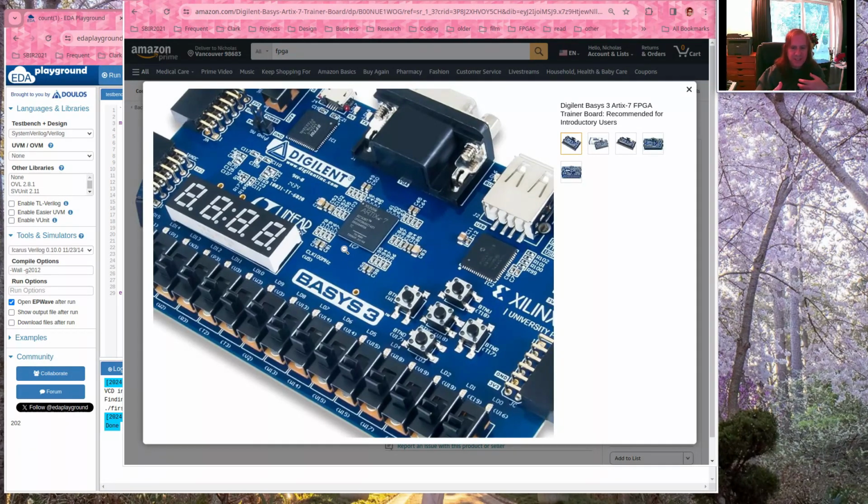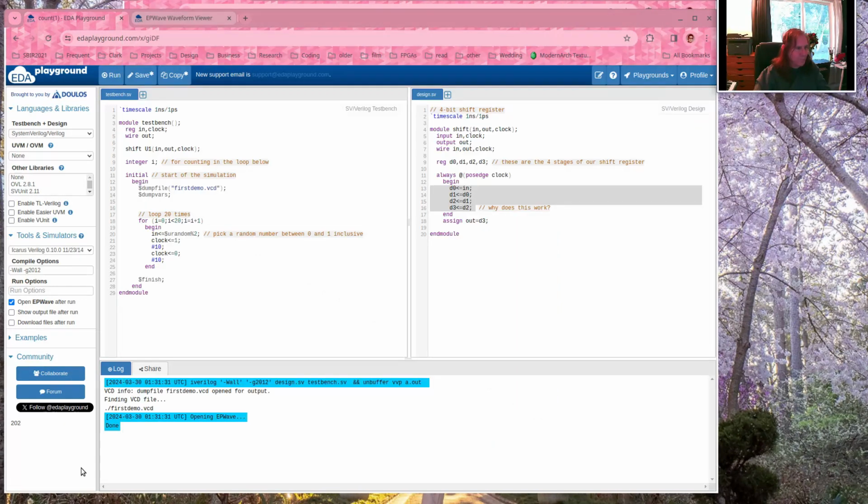Instead of designing a custom chip that's manufactured in a foundry out of silicon, people use FPGAs, programmable gate arrays, and it's cheaper. It's reusable. If you make a mistake, right, if you forget to set something to the right value in here, and you miss it in your simulation, you get your chip and your circuit's not working, you don't have to throw the chip away, right? You just fix your code, retest it, reprogram the device. If you do this on a foundry, right, that's a multi-million-dollar mistake.